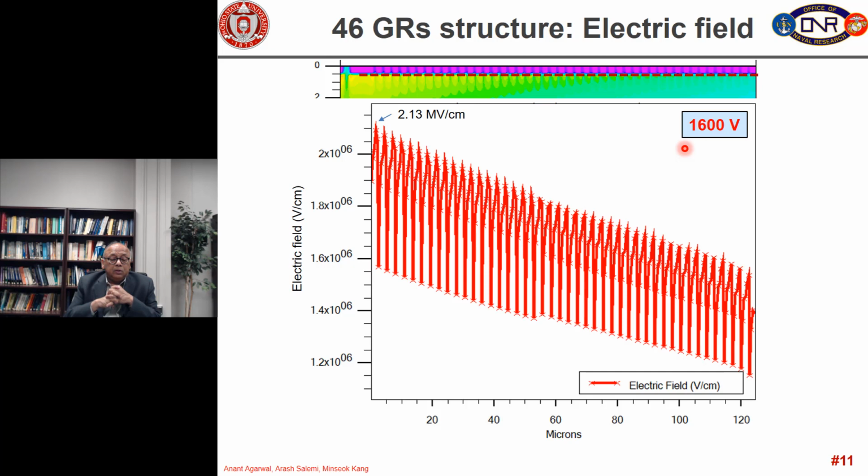So, the value of this peak electric field is not very correct in these simulations because electric field is obtained by differentiating the potential, and then depending upon how good your grid and mesh is inside the guard ring during a simulation, that can affect the peak value. So we don't pay too much attention to this peak field, but it gives us a good trend.